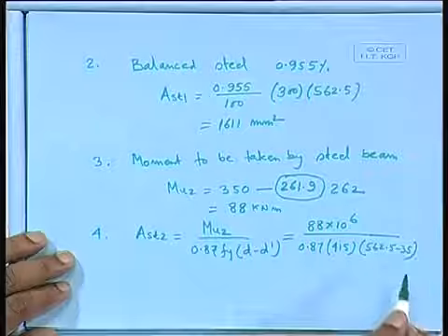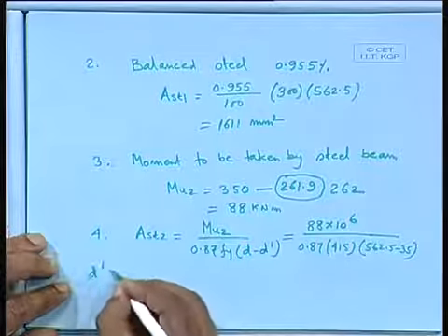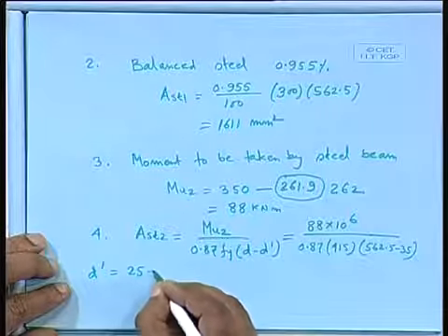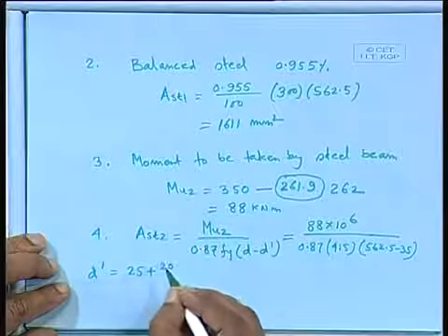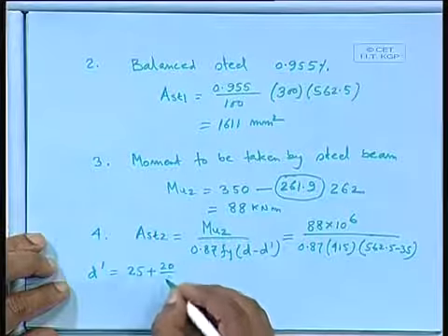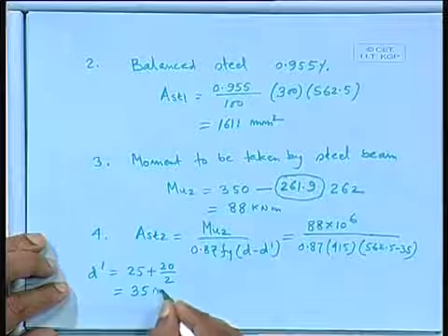Here d dash, let us say again, we shall provide 20 millimeter dia bar at the top, which comes as 35 millimeter.